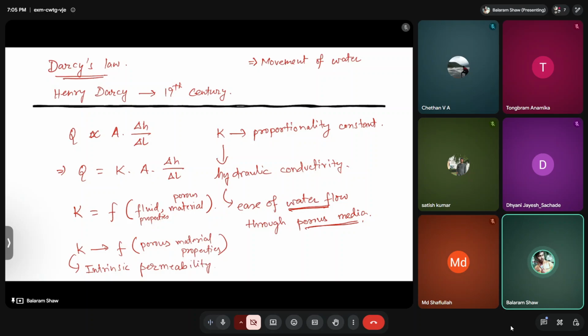In many places, many studies, you will see that we use the hydraulic conductivity and the coefficient of permeability equivalently. However, there is a small difference. But if the effect of fluid is not substantial, then we can consider the hydraulic conductivity and the coefficient of permeability as equal. In many theoretical problems, not real-life scenarios, we consider them the same.